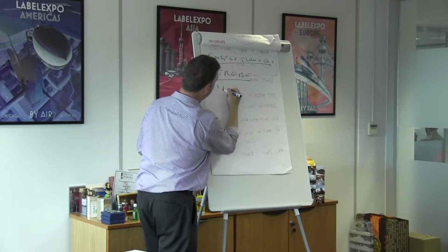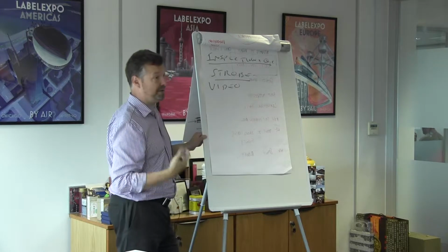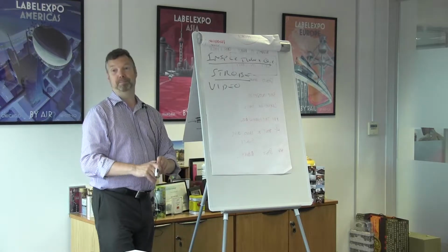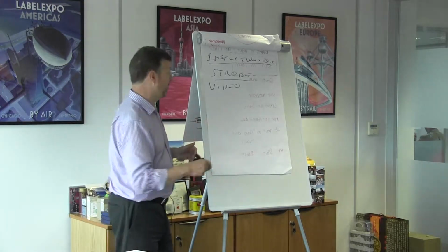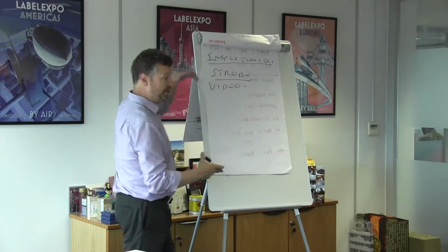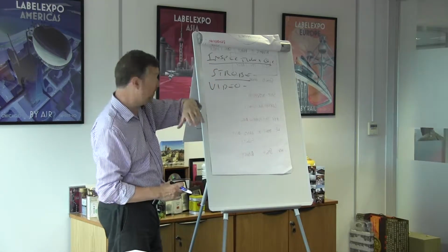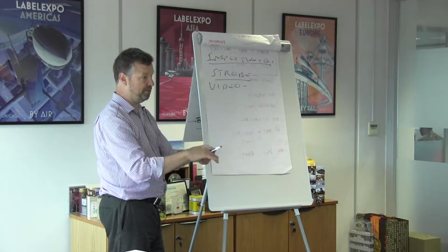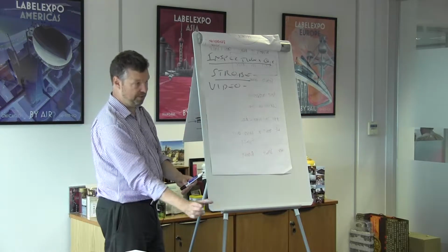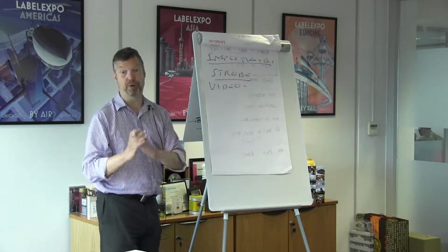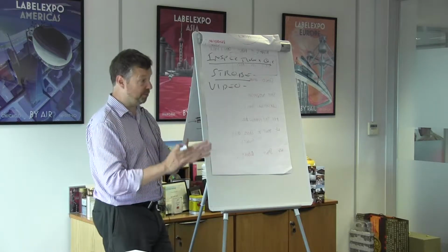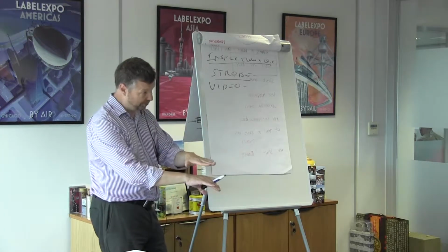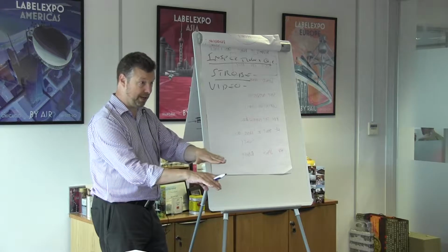So the video camera, and again, this is where all of our main guys, AVT is obviously the leader, BST, Ultramat, PC Industries, there's a whole bunch of companies out there who do video. It's basically a high resolution video camera. It just sits over the web. It's normally on a moving platform because the aperture can only cover about 2 or 3 inches, so it can't look at the whole web unless you've got special 100% web inspection systems which do cover the whole web. But generally speaking, you'll see them on a little motorized chassis like that, moving across the web, scanning across.